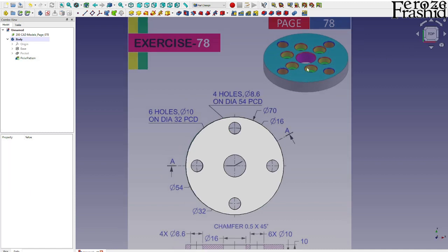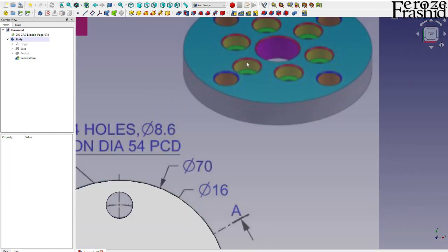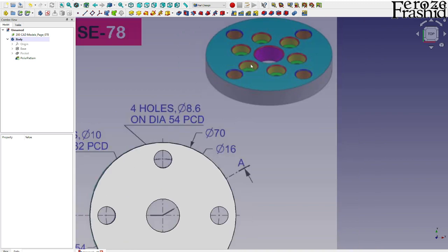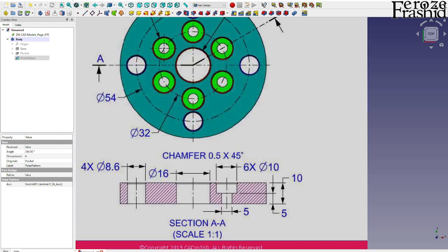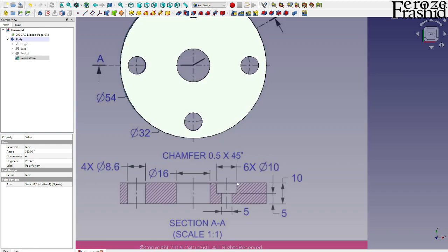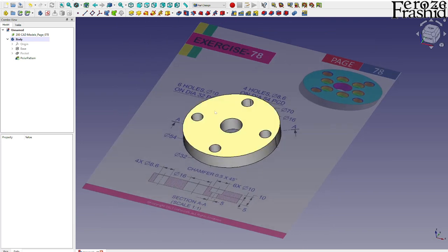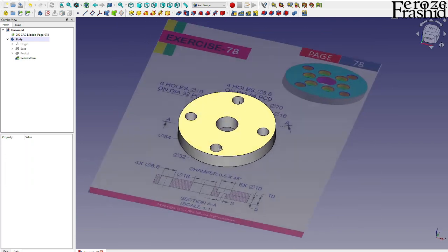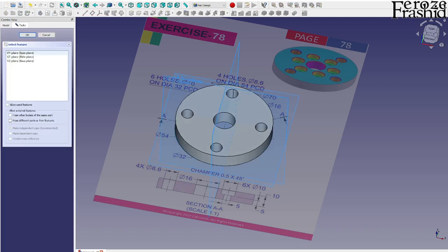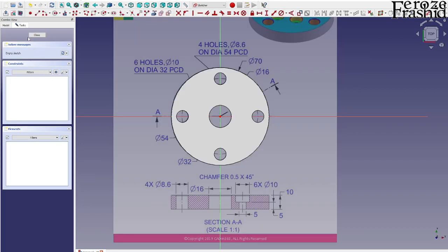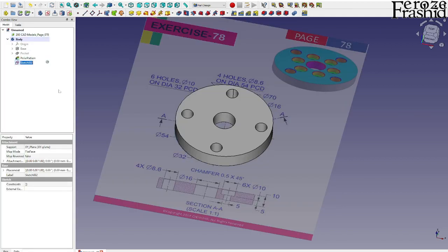Now let's take a look at this hole, which looks like a counterbore hole to me. Here we can see it's an outer diameter 10 millimeter and inner diameter 5 millimeter, and it's halfway through. It is 5 millimeter on both sides. So I can do that, but I want to place that sketch on top of here. One way to do it is select sketching, XY plane, hit OK, and now close it. So we know that this is the sketch, so it will be sketch hole 2.